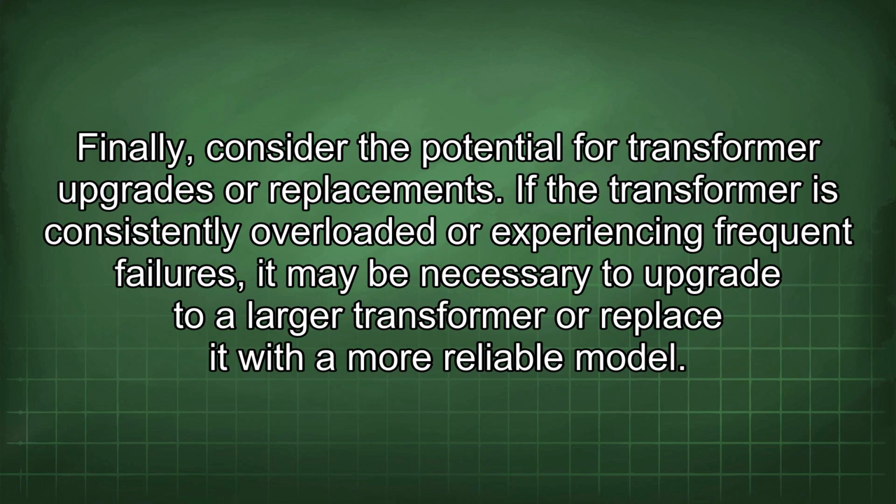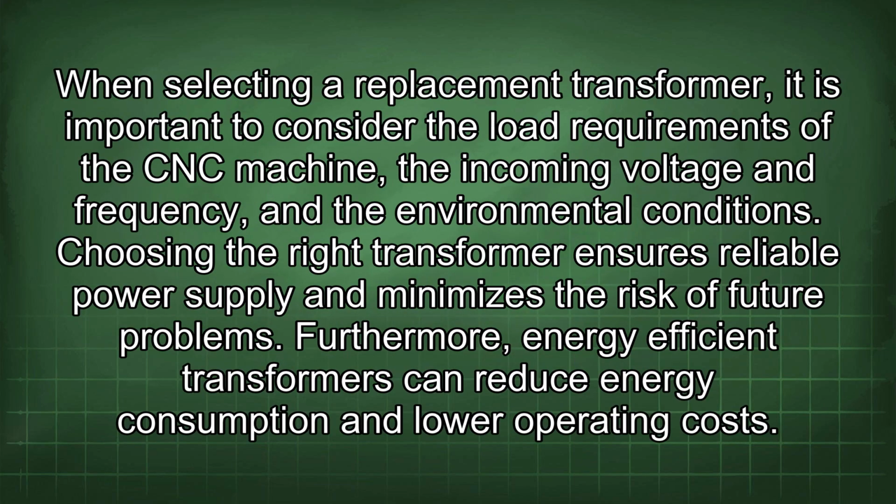Finally, consider the potential for transformer upgrades or replacements. If the transformer is consistently overloaded or experiencing frequent failures, it may be necessary to upgrade to a larger transformer or replace it with a more reliable model. When selecting a replacement transformer, it is important to consider the load requirements of the CNC machine, the incoming voltage and frequency, and the environmental conditions. Choosing the right transformer ensures reliable power supply and minimizes the risk of future problems.